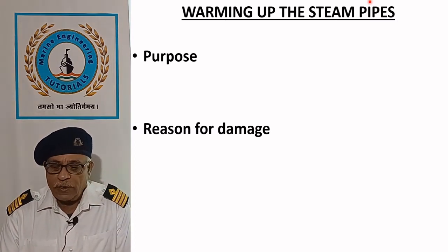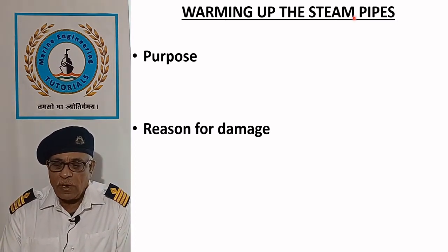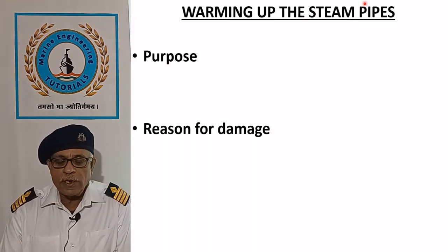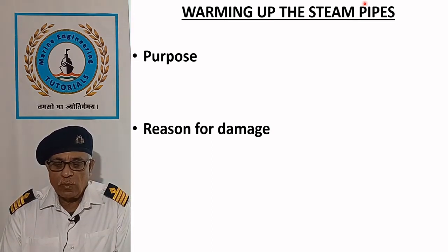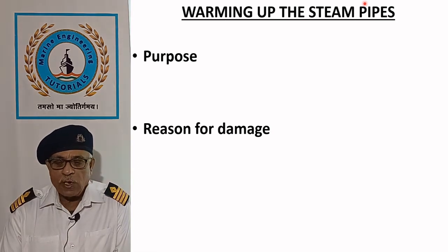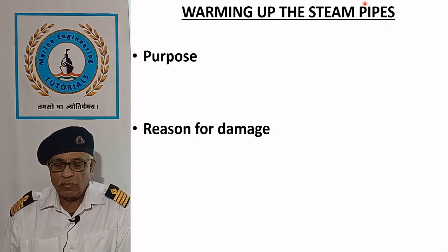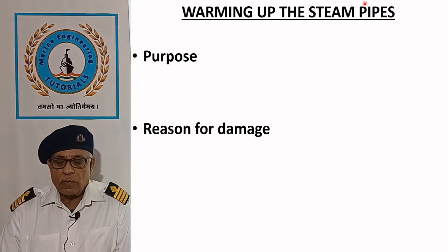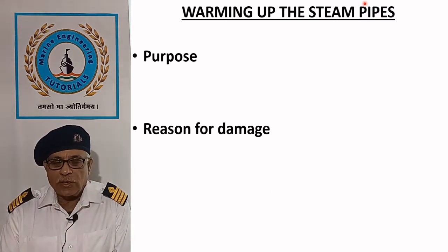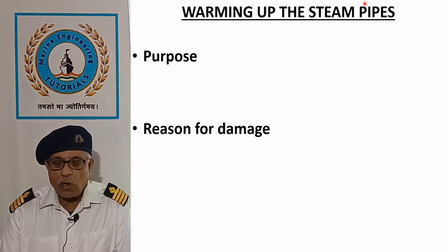When steam is admitted, its condensation occurs on the cool water surface or in a cold section of the pipe, resulting in a partial vacuum due to which water moves along the pipe at great speed. The impact of this water at the bend or wall can cause fracture of the pipe. Water hammer is indicated by severe and often repeated banging in the pipe.